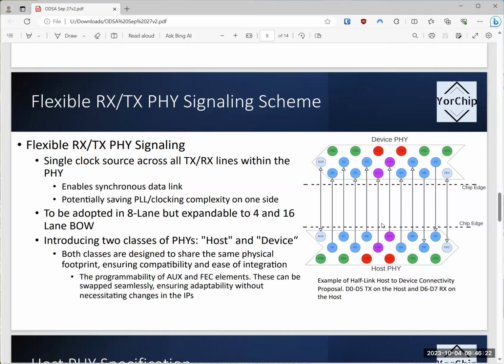Okay. If I understand you correctly, what you're saying is this bidirectional slice can only operate in a single direction when it's talking to another BoW slice. And so if you now need to get data into and out of this chip, you're SOL basically. Well, or you just have to use two of these PHYs if you want to do that, in which case the point of being bidirectional is lost, though there may be some other merit to being bidirectional outside the scope of the spec.